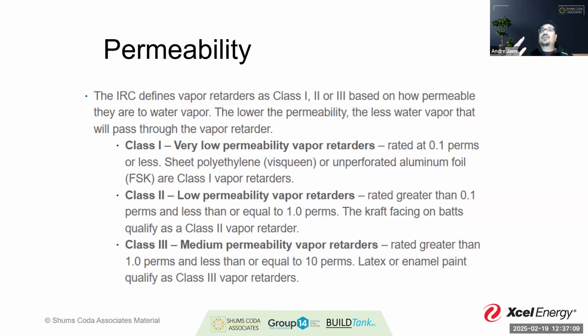And you get to explain to them, no, what you have done is you have created basically like a steam box, right? Where any moisture that was ever in that system will live there and just continue to condense and continue to rot in that space because you're not telling that water where to go and why. You're not doing it with intentionality. You're closing it off because you think you're using the best products on the market without regard for why they tie together and how they tie together.